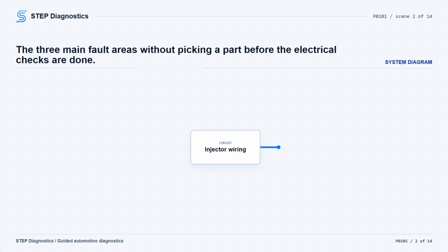Also use care around energized injector wiring. These injectors use high voltage to operate, and contact with exposed energized wiring can cause serious injury. If regeneration starts during testing, let it finish before continuing, because values may be biased during that event.